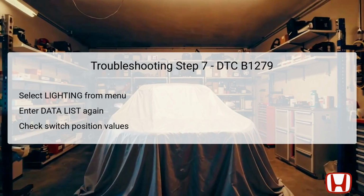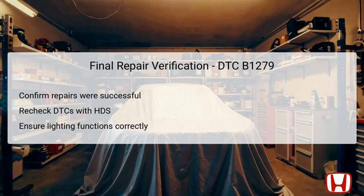As before, you will check each of the combination light switch position values presented in the data list. Pay particular attention to the various states of the headlight switch as it is tested in different positions, including off, high beam, and the passing position. This step enables technicians to evaluate the functionality of the newly analyzed switch without any possible discrepancies caused by earlier wiring connections. After completing the troubleshooting and any necessary repairs related to DTC B1279, a final repair verification is essential.